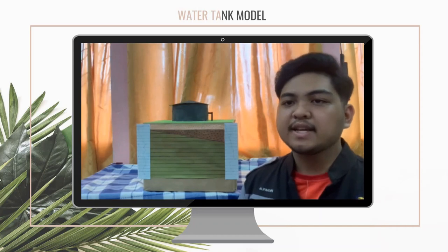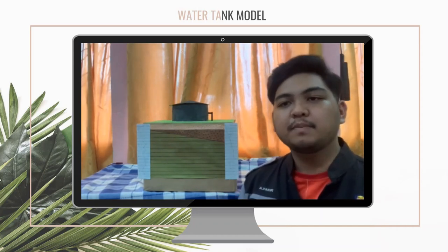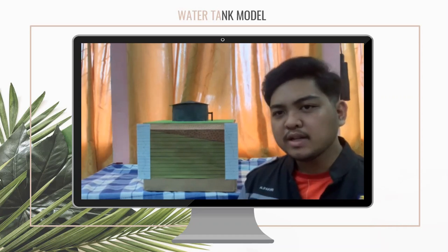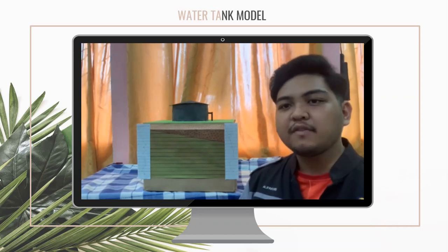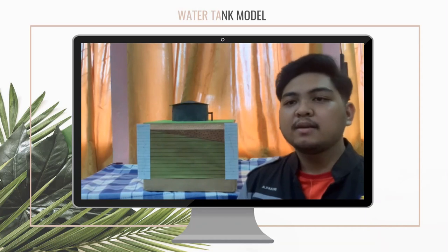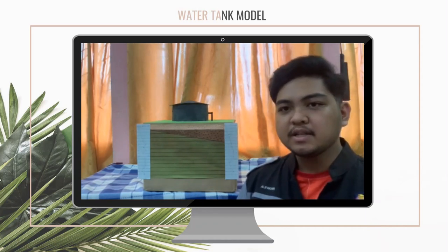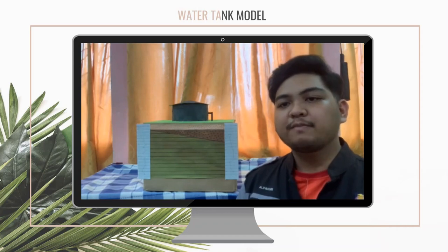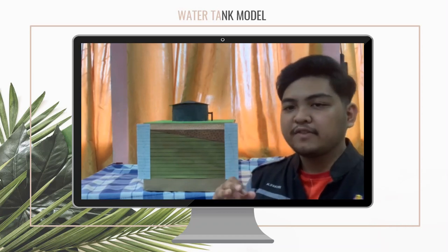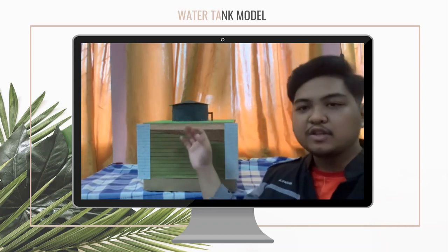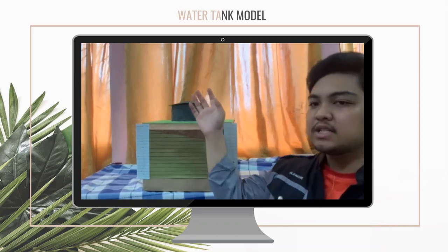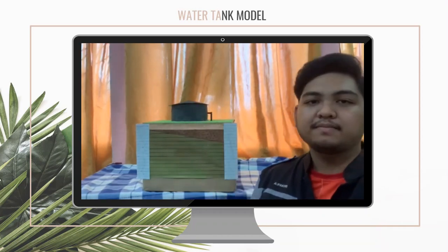Borehole 1 silt layer has a bearing capacity of 145 kilonewton per square meter, while borehole 2 clay layers have a bearing capacity of only 95 kilonewton per square meter. The higher the bearing capacity rating, the greater the load or pressure that may be given to the foundation structure without destroying it or the structure that sits on top of it.